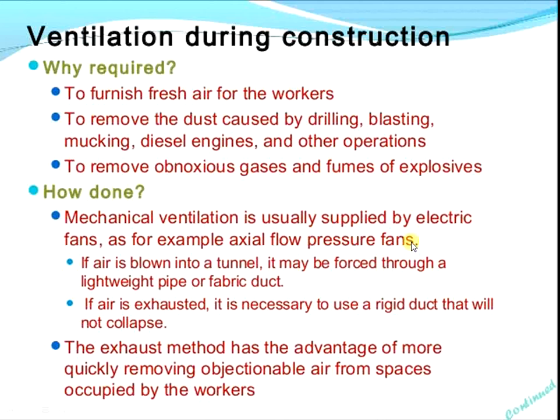There are two types of ventilation. The first is mechanical ventilation and the second is natural ventilation. In mechanical ventilation, we have to provide electric fans, for example axial flow pressure fans. If air is blown into the tunnel, it may be forced through a lightweight pipe or fabric duct. If air is exhausted, it is necessary to use a rigid duct that will not collapse.